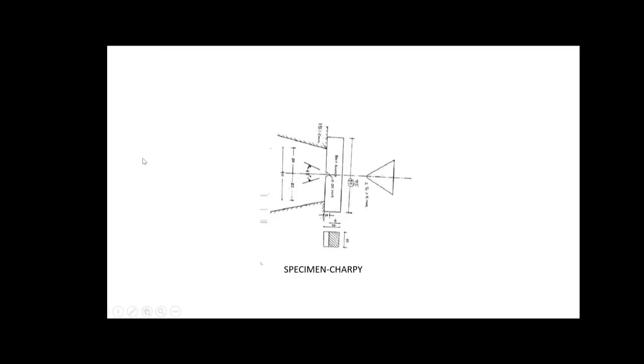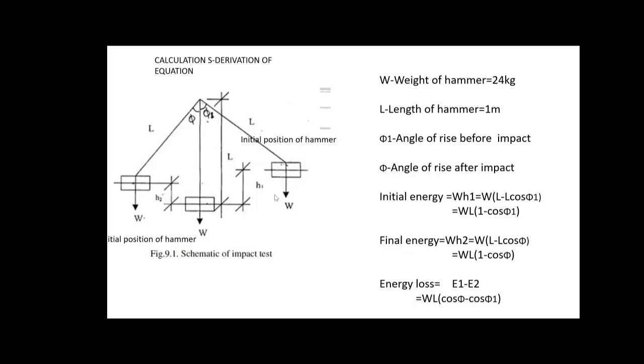For conducting the Izod test, we are using the flat end, whereas for conducting the Charpy test, we are using the triangular end, so that we can change it in the hammer. Within the hammer, it is just screwed, and we can loosen it and change the position according to the test that we are conducting. Here the load is applied as a central point load with the impact loading using the hammer.